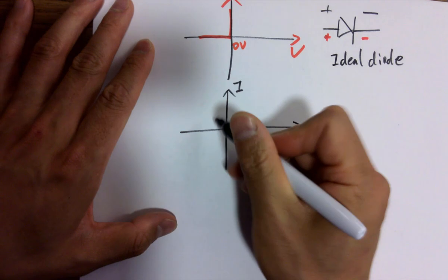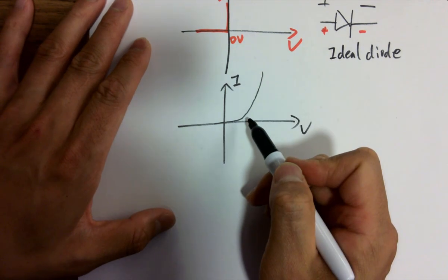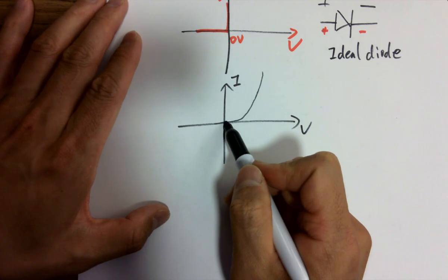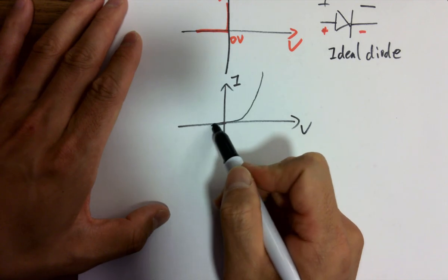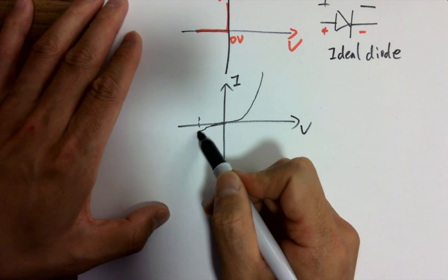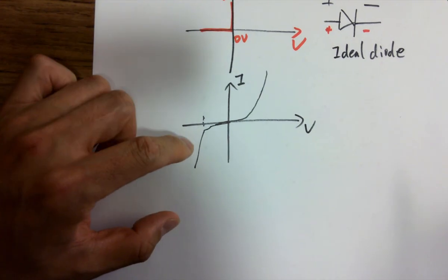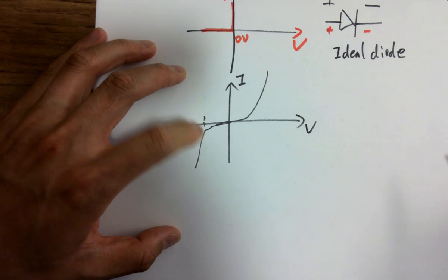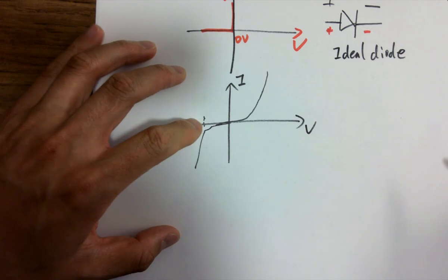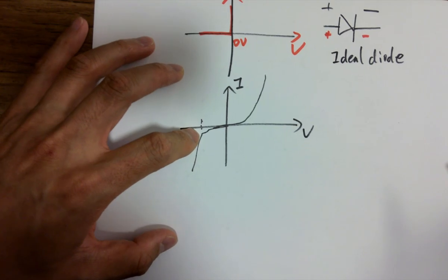It works this way. It's very similar to the VGS to IDS of the unknowns. And when you reverse bias it, when it reaches a certain negative voltage, it breaks down. So for a regular diode, it's going to be broken. For a Zener diode, you are actually using the breakdown condition to stabilize the voltage. Have you used the Zener diode for circuits before? You have? Anyone else?